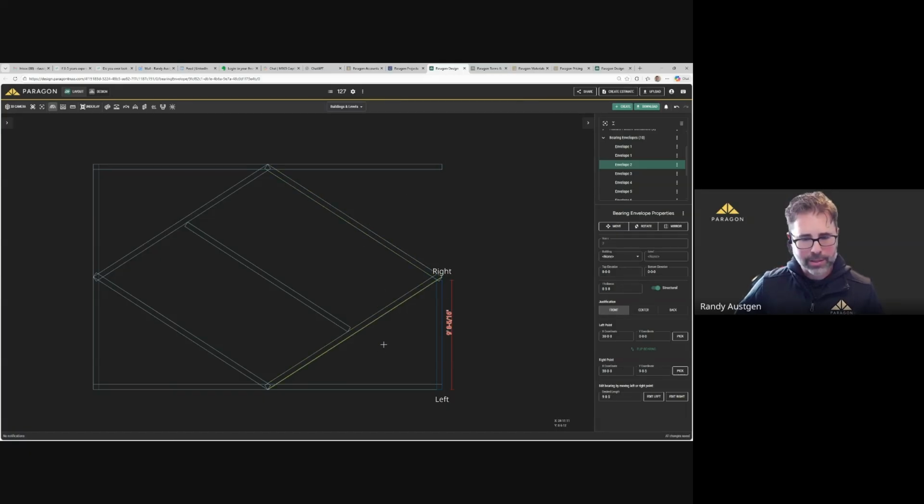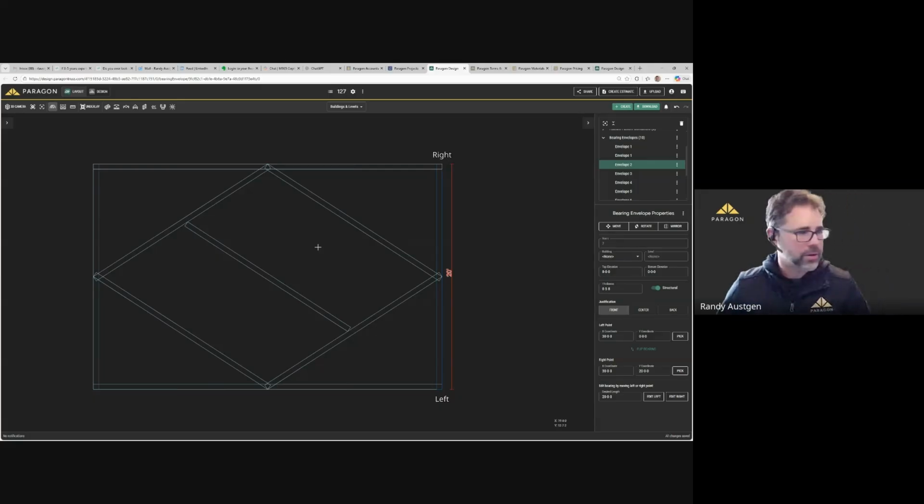Oh, here's maybe an example. There you go. So you can kind of use that while holding down shift. That's a pretty quick way of doing things. I've done that quite a bit in design mode, when you're trying to adjust the length of maybe a web or something, to get those intersections proper.